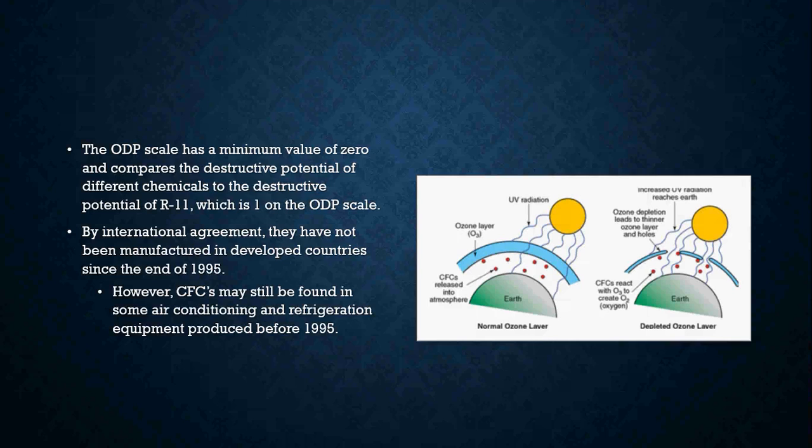If you can never read the nameplate for the type of refrigerant that is in a piece of equipment, you can always go by the model and serial number. Everybody has a smartphone, an iPad, some sort of electronic device where you can punch in these numbers and do a little bit of research, a little Googling, to find the type of refrigerant that you're actually dealing with.